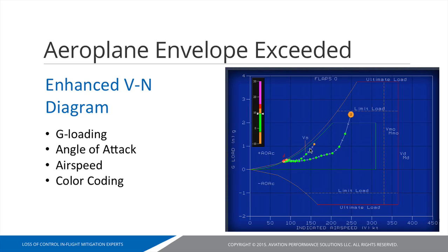What this does is represent a margin of safety that the pilot has in any one situation away from the stall. For example, we can see that the distance from this particular plot to the CLmax position is pretty significant. So we could conclude that there's a large margin of safety between the CLmax, or angle of attack, of the scenario and where the airplane is.